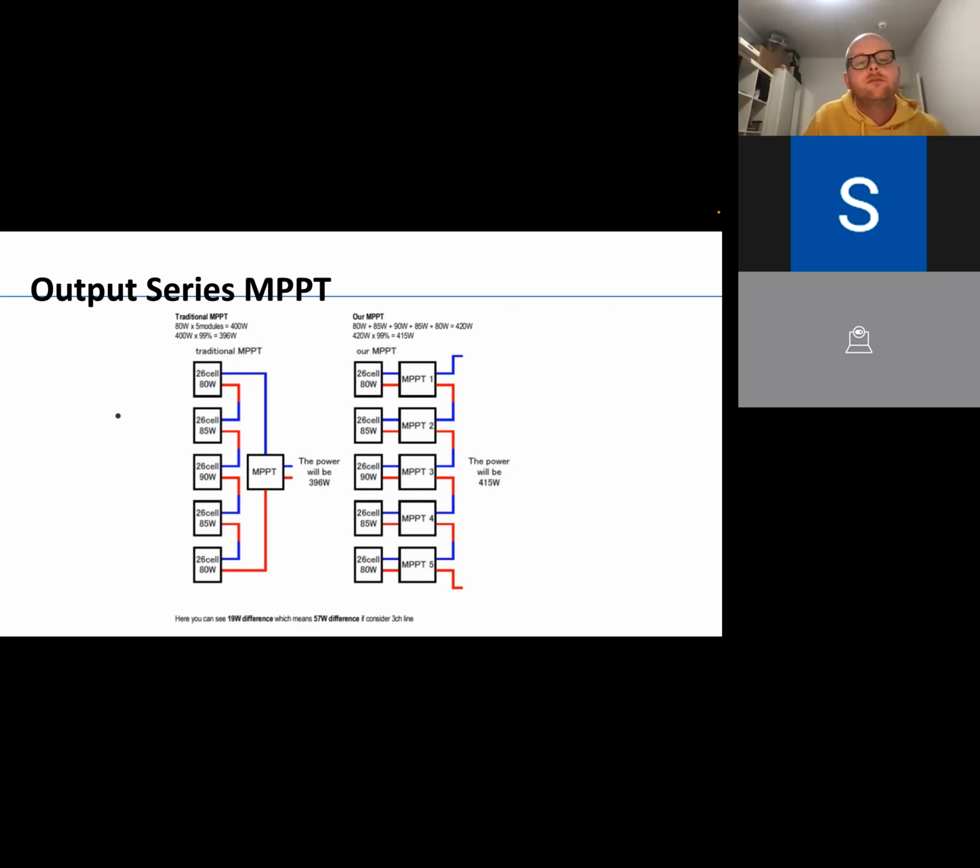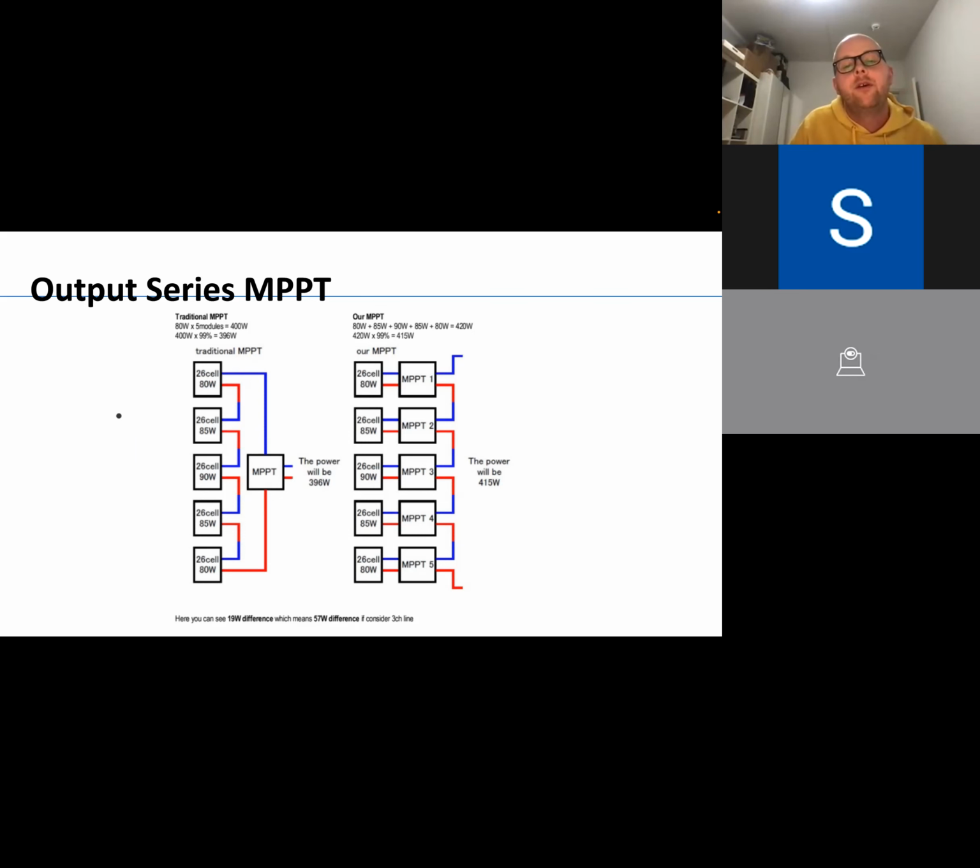It would give you a little bit of a different IV curve. You can trace IV curves in 2 different ways, right? You can start with the maximum voltage and then go down to 0 volts, or you can start at 0 volts and then go up to the maximum voltage of your solar array. With smart bypass diodes, depending on what direction you're going, you get a different curve. The reason for that is that the diodes take a little bit of time to turn off.